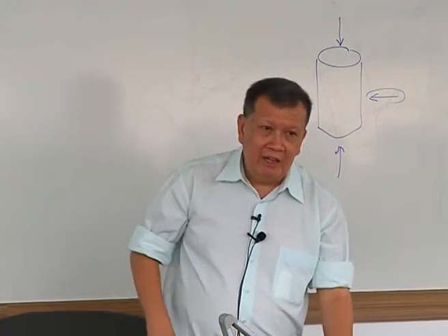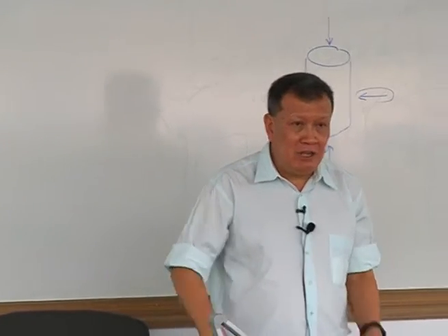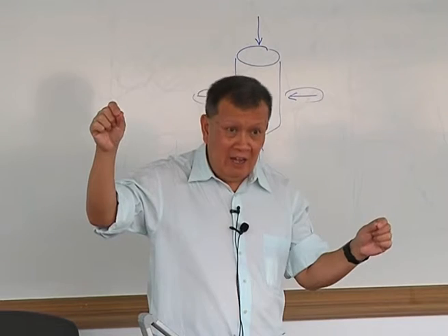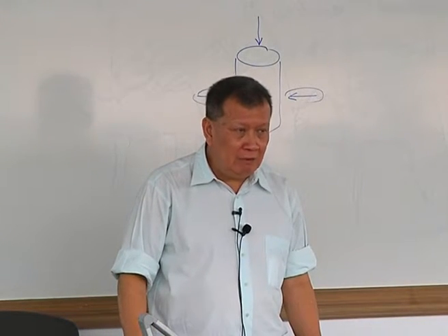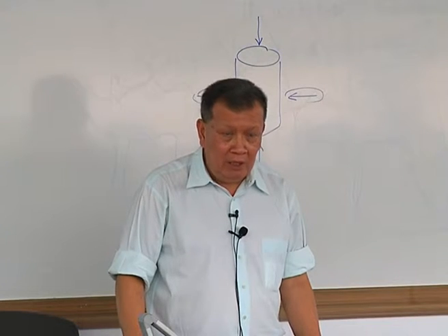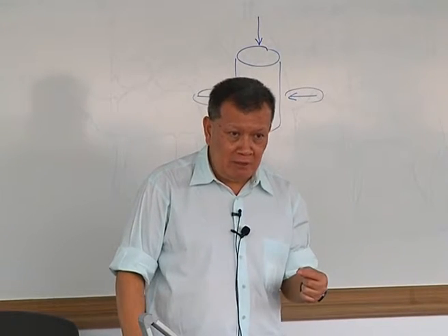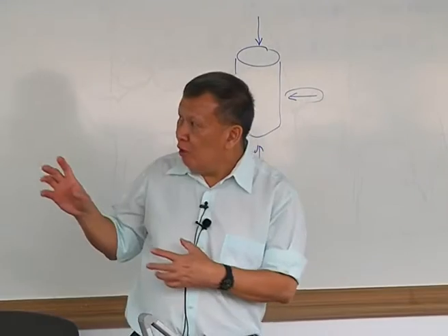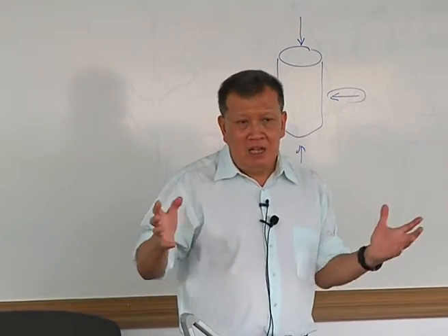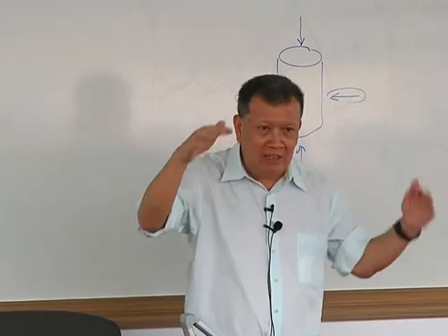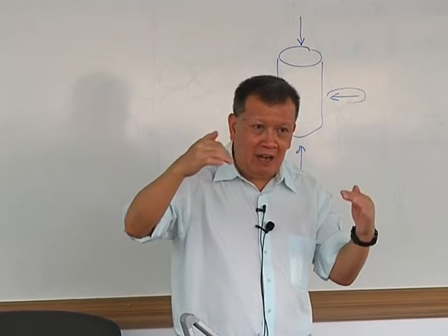You can, because the plastic potential has a plastic potential function. But usually if you're dealing with something simple like Mohr-Coulomb, you don't need to go to that plastic potential function. Later on, when I go into Mohr-Coulomb, I will give you an example of what the plastic potential function looks like, because it's actually quite simple. It's a series of lines, and it's defined by a certain class of function.